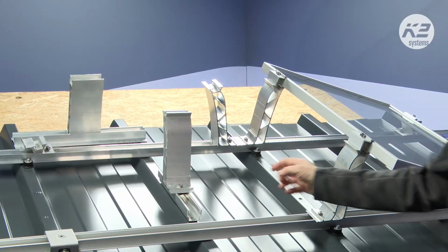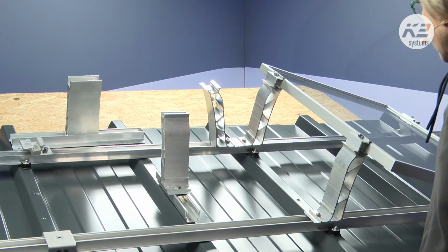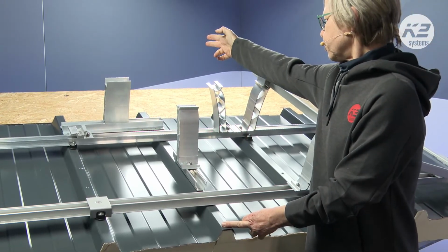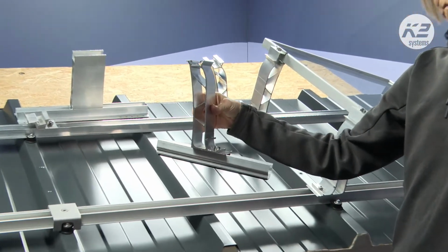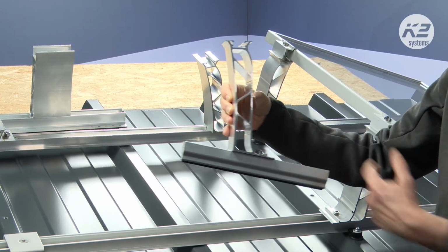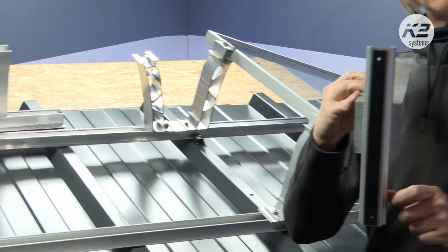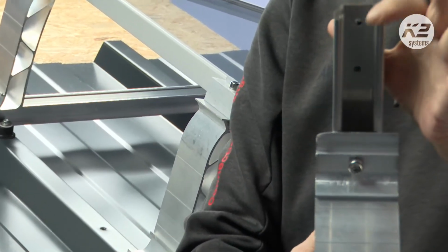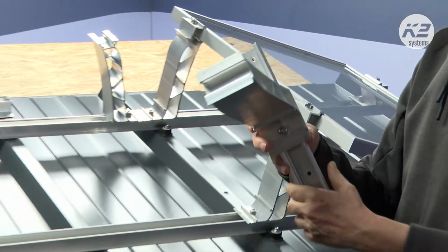And you see the differences. One is the rail. The second is that here we do not have a long running rail, that means a rail that runs maybe to the top of the roof or the end of the crest. We have always short rails. They are 25 centimeters long, and Base then also calculates the distance where you have to put these small rails, and they have to be fastened always with 4 screws. Two screws here, and on the other side the other 2 screws. So you fasten always with 4 screws.